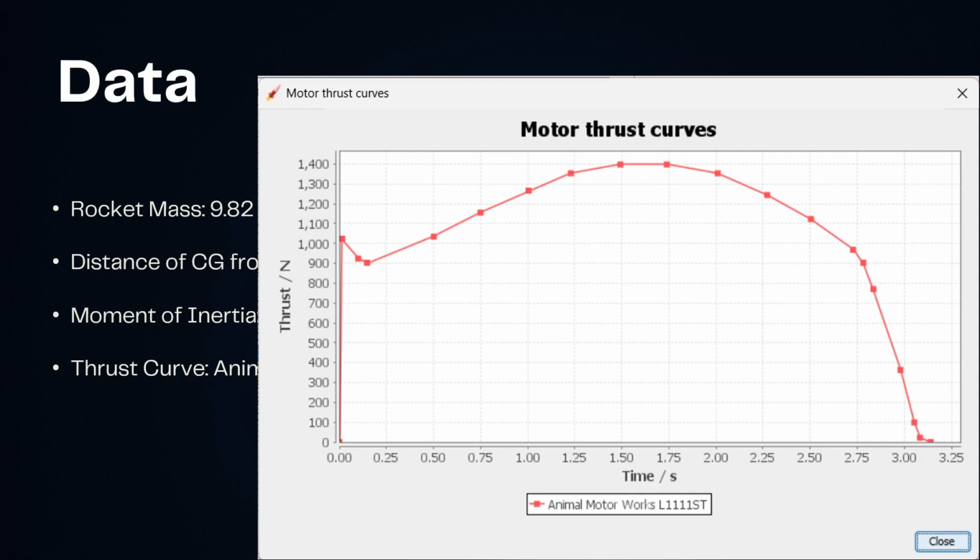It's a solid rocket motor, but you can consider any thrust graph you want, even a constant thrust with time, because it will be simpler and easier to implement. So, if it is easier for you, you can just assume a constant thrust, which is a reasonable assumption. You should take a reasonable assumption, and it will remain constant for the whole time, because these actual thrust curves only provide thrust for a certain period of time. Here the burn time is only about 3 seconds. Then the TVC can be implemented only for 3 seconds. So if you want to change the thrust curve, you can assume a reasonable value of thrust, even a constant value if you require.